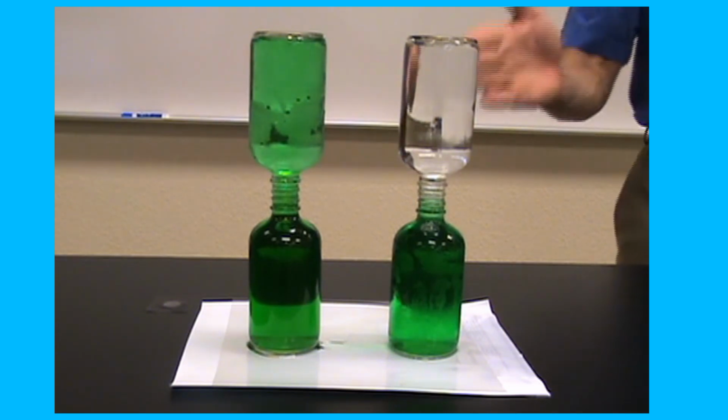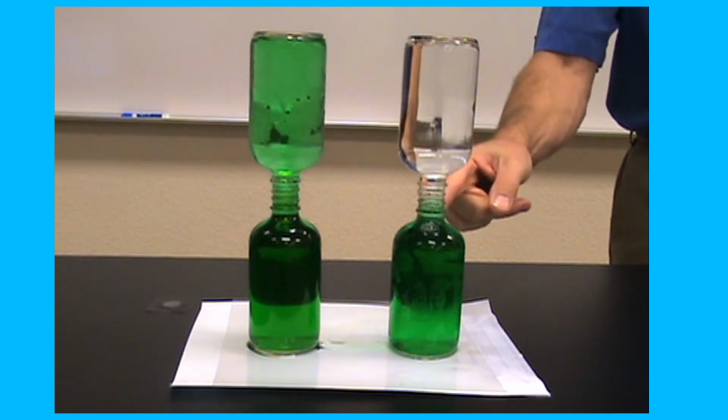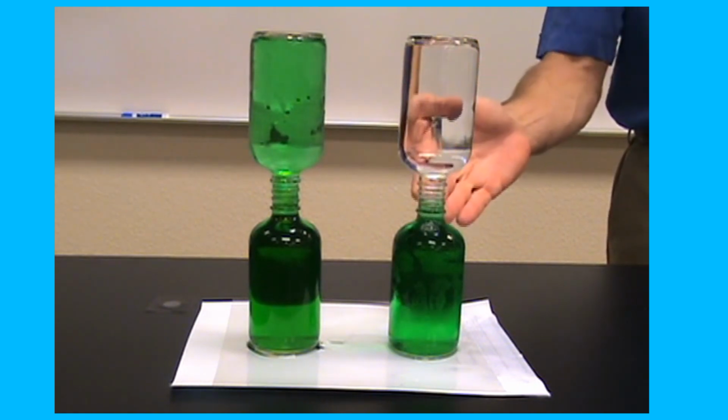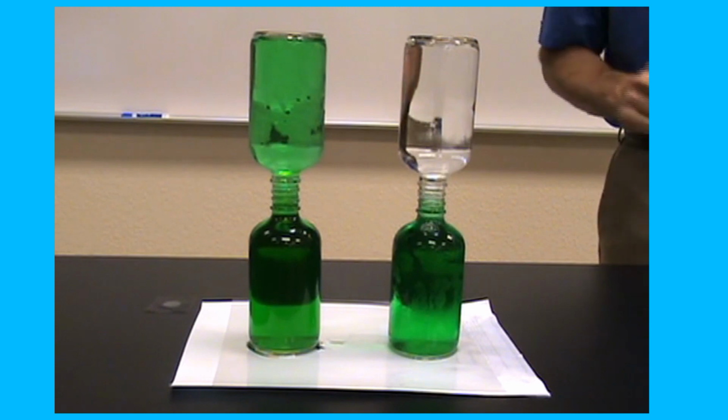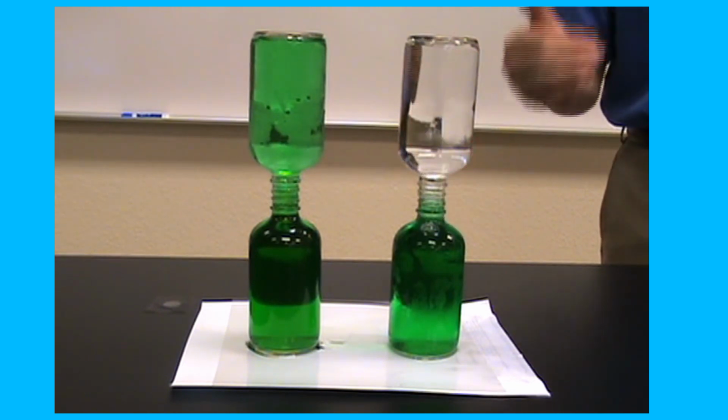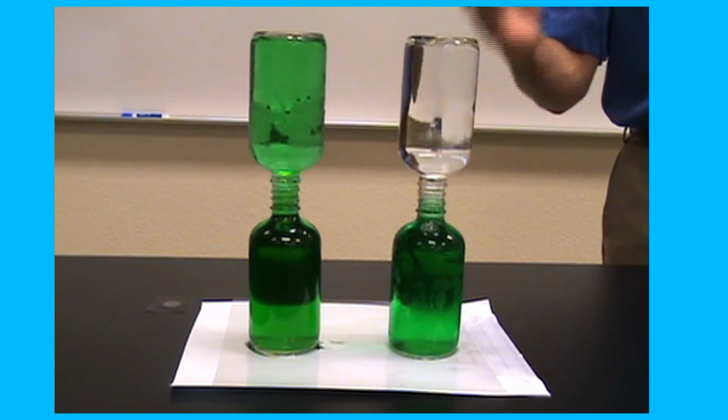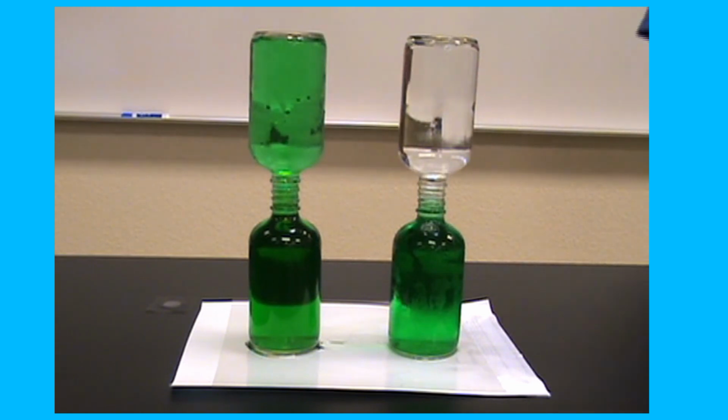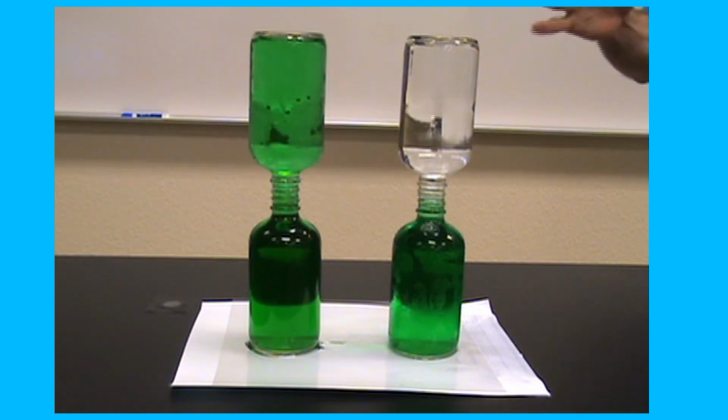When we have the inverted bottle here, we see that the cold water on the bottom is more dense, less buoyant than the hot water above it, so we don't get any of this natural convection to take place. We don't get any natural mixing. So this is happening in the atmosphere around us all the time, when it comes to air and other fluids like water. But by putting a few drops of food coloring in this, we can see these convection currents that get set up in one case and don't get set up in the other.